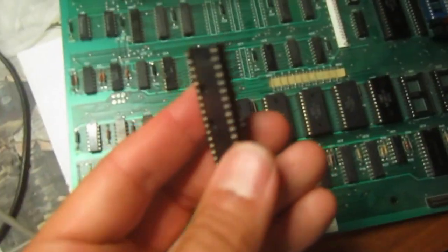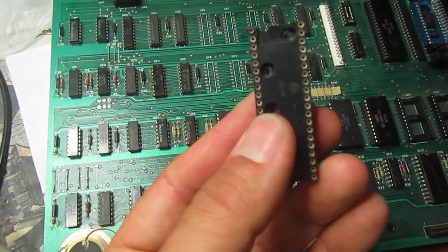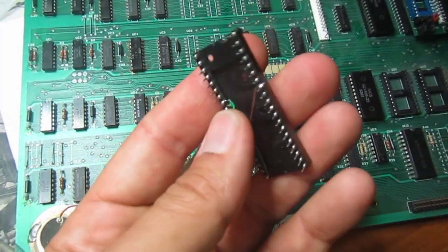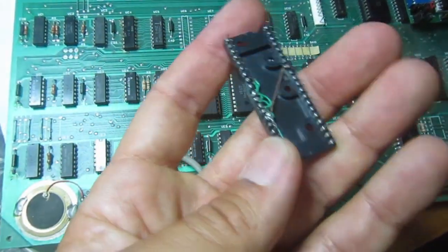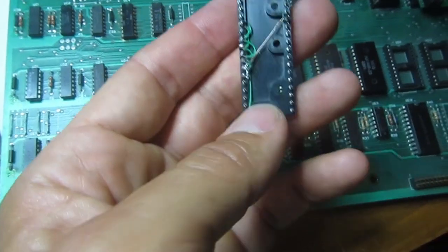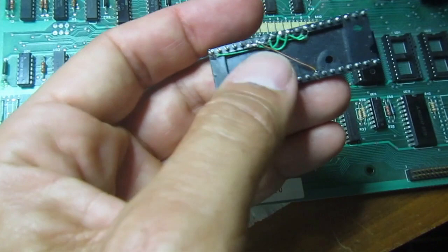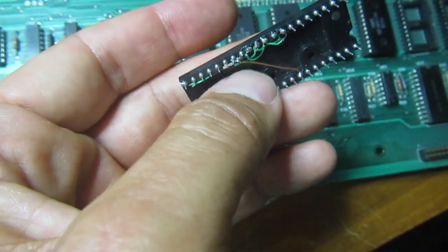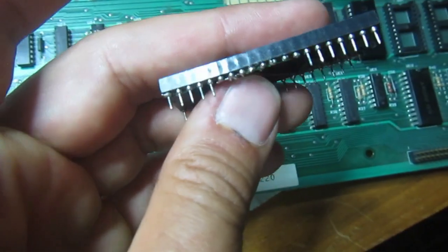I think I will install a NOP generator socket on the 6502, and that will allow me to observe the address bus cycling, because with this NOP generator the data bus is disconnected from the machine, and the 6502 always reads hardwired data which corresponds to the NOP instruction.